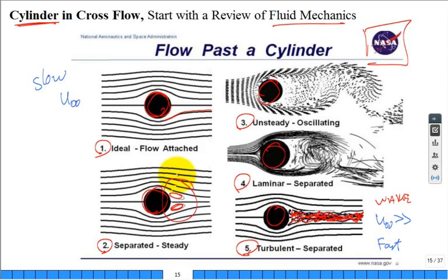And then when the flow gets a little faster, what are they showing here? It's like little vortices that spin off. It's a von Karman vortex street. It's getting more and more unstable as the flow speed goes up. The Reynolds number is going up. And then they get this big separation region. Now there's some very good structure in here with the recirculation. There's less structure to the flow, but there's still a pattern of this tail, this shedding of vortices.